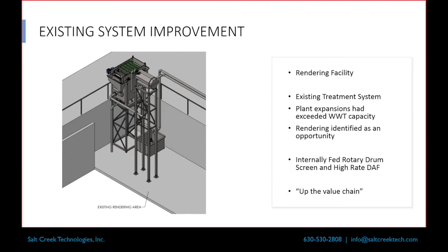And then we came up with one solution to actually do some FOG recovery at the rendering facility, at the rendering plant specifically. What was interesting about this was it's an internally fed rotary drum screen and a DAF. That's not too exciting, but we were able to get a pretty good recovery off of the DAF still of FOG without doing any chemical treatment.